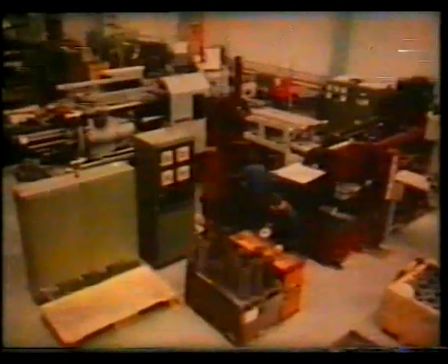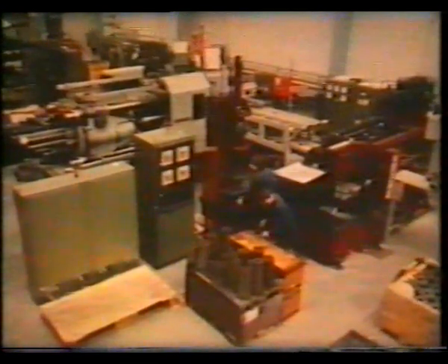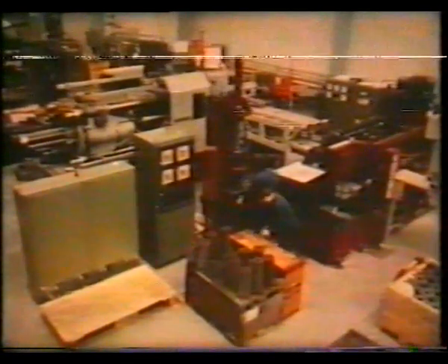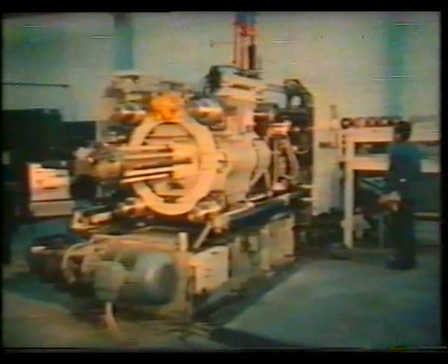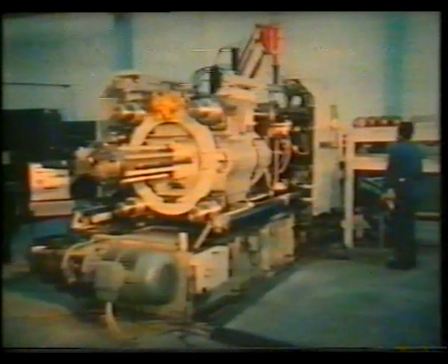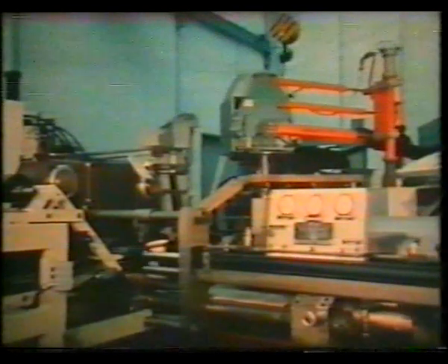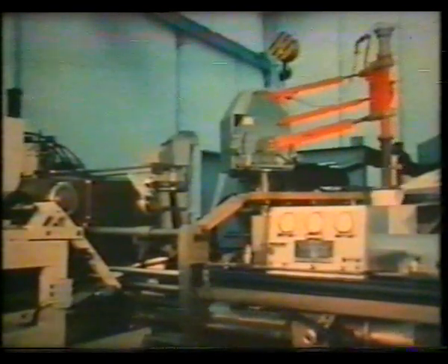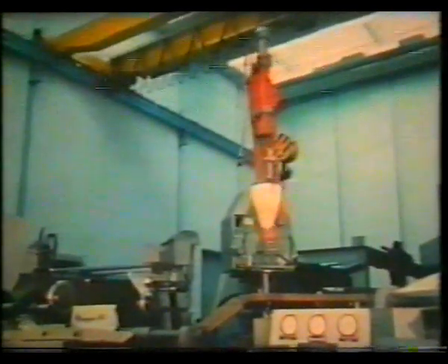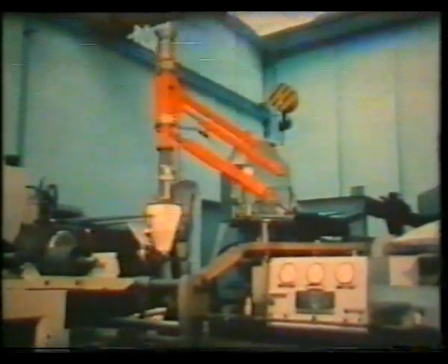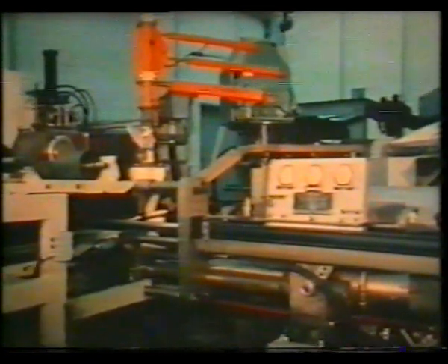From stacking to deburring the rotors and pressing out the mandrels, the facility carries out all the necessary process steps. The heart of the system is the die casting machine with 6,600 kilonewtons locking force. The Filmat ladling unit by Buhler feeds the liquid aluminium into the die casting machine. The required amount of metal is taken at an accuracy of plus or minus 1% and transferred to the pouring hole.